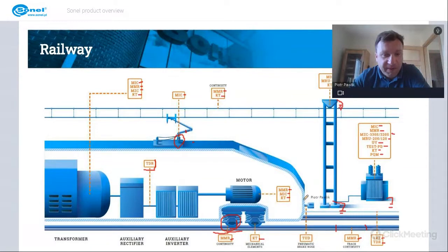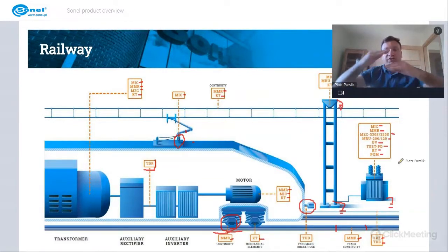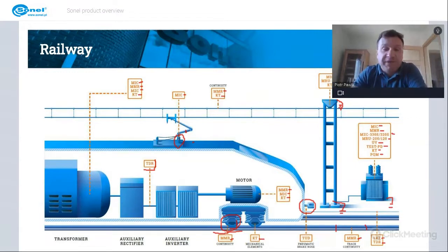At the end of the train engine and between each of the wagons, we have pneumatic connections. They are mostly used for the brakes on the wheels of the trains. Now we need to make sure that there are no leakages in this pneumatic system, and we can do this using the ultrasonic leakage detector, the TUD1. Of course, in case we get a leakage, then the brakes may not work correctly on the train, and we wouldn't like to be on such a train.